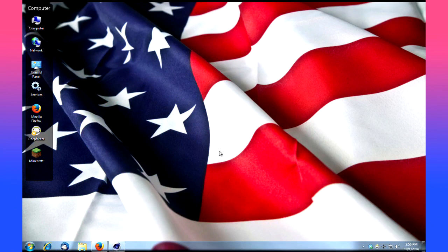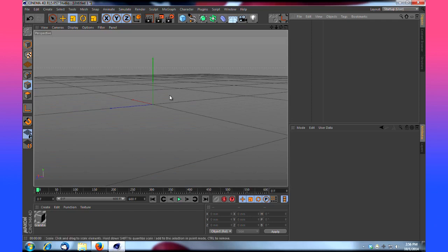This one stems from a question asked by one of my subscribers who was wondering how you might go about modeling a round structure. And I guess you could go about that a variety of ways. You could use a cylinder, manipulate its face, and apply different textures to achieve that look. But for this example, I'm going to use blocks that you might see in a typical concrete block construction or a stone construction. And we're going to facilitate that further with some cloners. So let's get started. I'm using Cinema 4D R15.